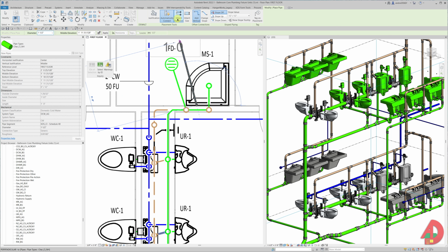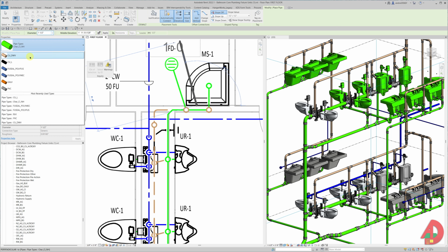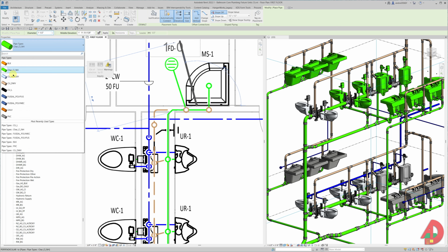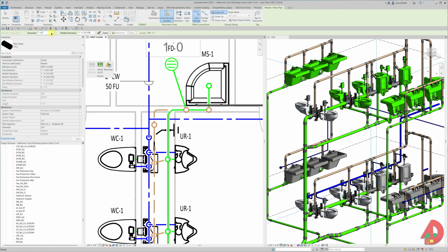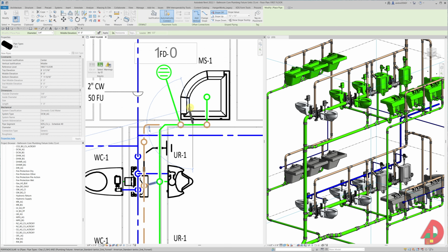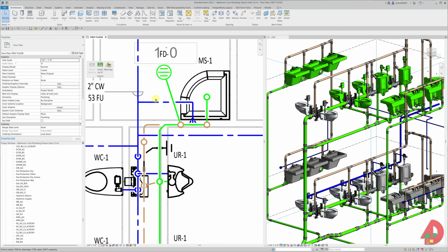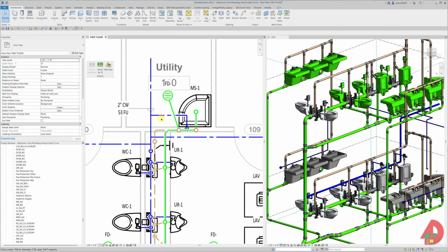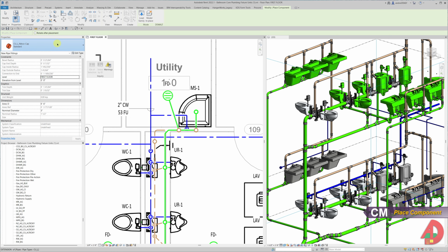Inherit elevation, and here in the properties panel it looks like my pipe is cast iron. I need to choose copper from the drop down and now set the diameter to 3/4 of an inch. I am drawing a short line that is still in the wall, then change the elevation to 8 to match the cold water line main, and then draw a line upwards and left to connect. If I choose so, I can also add a 3/4 of an inch shut-off valve.